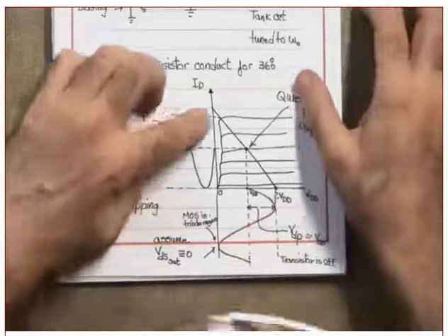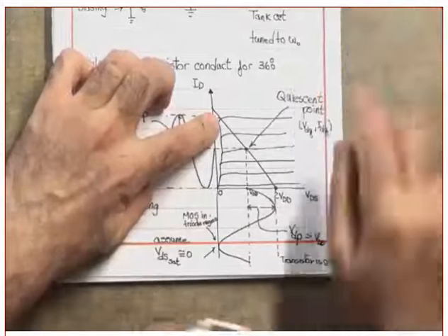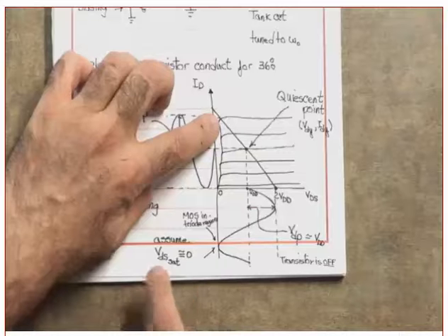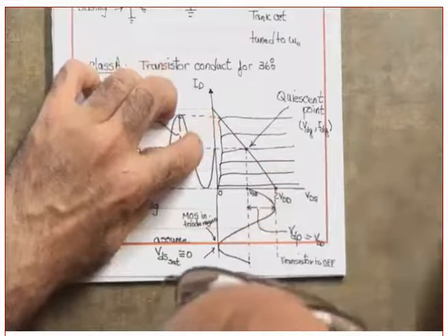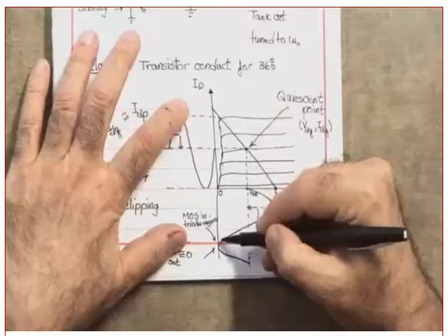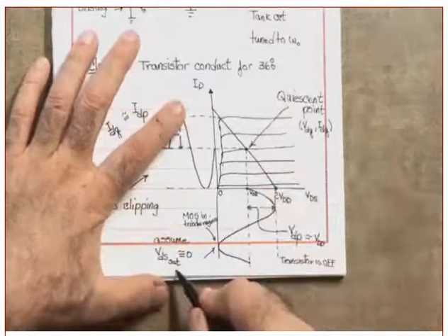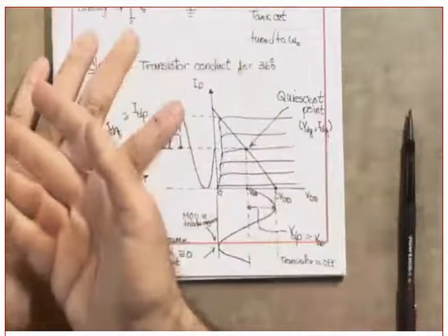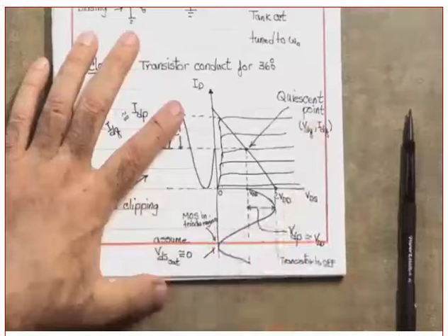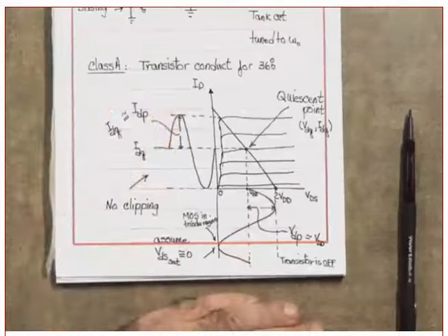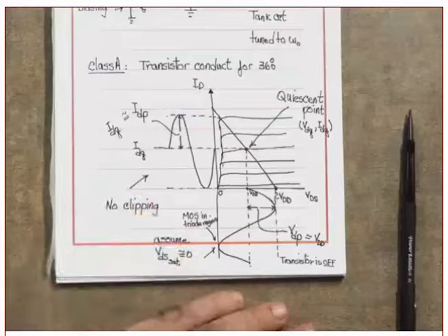Agree? Now, in here, I am making a slight approximation. I am assuming that the saturation, are you familiar with the saturation voltage? The VDS saturation is approximately equal to 0. Because this one actually should go only to this value. Did you understand that or not? But for simplicity, I'm assuming VDS sat, which is typically, anybody? It's roughly 0.5 volt or something like that. Yes or no? I'm neglecting it so that I can show you the full sinusoid. Clear? No response. Clear? Question.